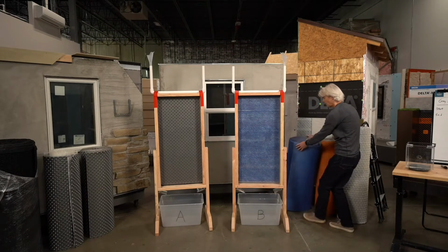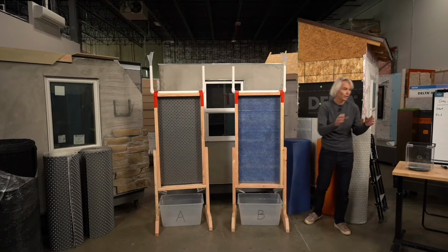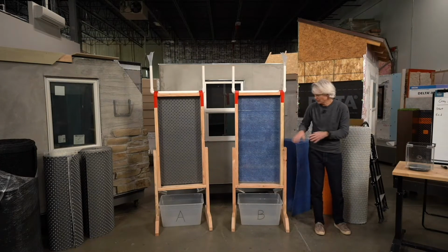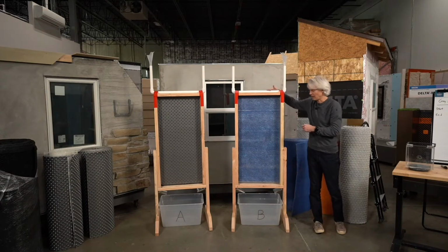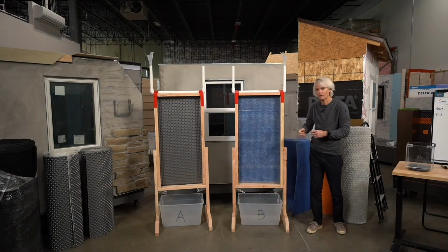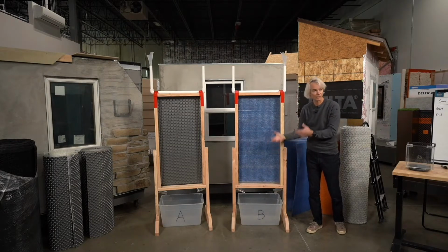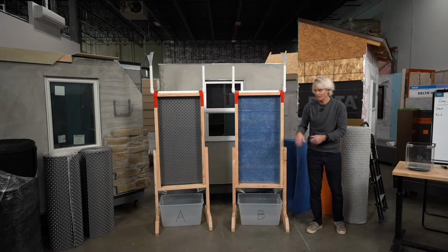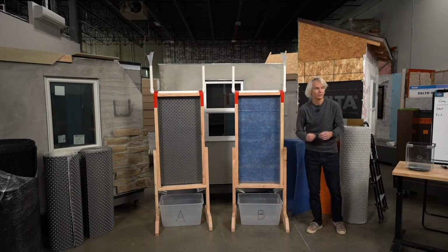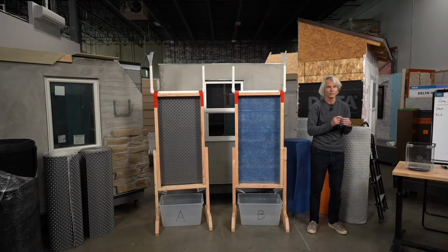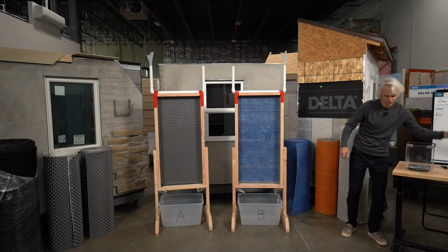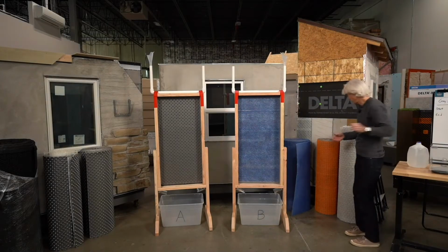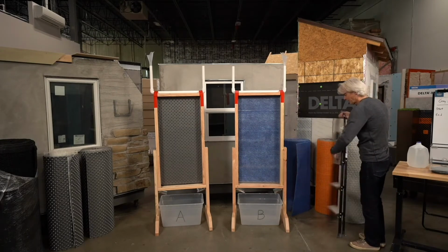So really our first part is we're going to take this sample and we're going to run a 15-minute test for that water drainage for both of these. So we're going to dump the water into the top of this tube here where we've built a rain shower, and it's going to come through this product. We're going to then let these products stabilize for 15 minutes, and we're going to collect and weigh the water samples to figure out how much is in the wall versus what's there. And the water weight that we're going to put in is 1 US gallon or 8.3 pounds. So as we first grab that, we'll get things situated here, and I'm going to need a step stool to get up there.